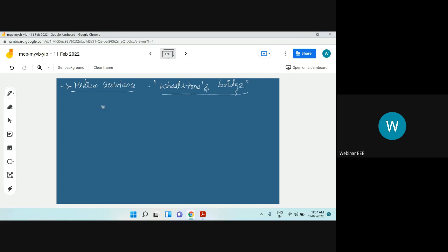So while coming to this bridge, this is how the connection will be. This is a bridge which you have learnt in your lower classes also. This is our basic bridge, and here we will observe a deflection galvanometer, and this is where the DC supply is connected, and the representative terms will be P and Q. It depends on the conditions of what variables you are going to take. This is a method which is used to measure a medium resistance value. Here the balance condition will be PS is equal to QR. So the product of the adjacent arms will be equal on either side.